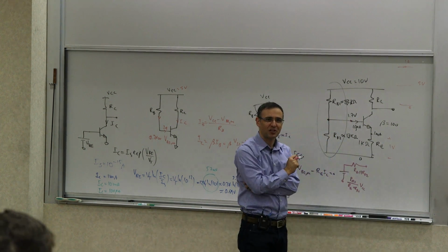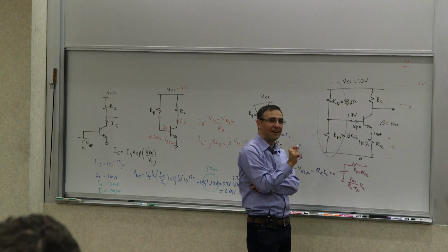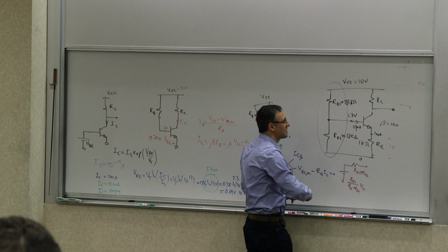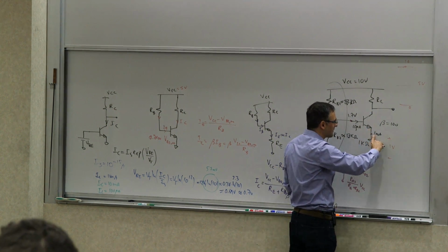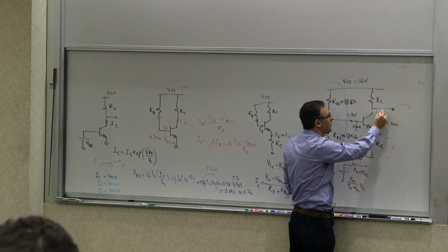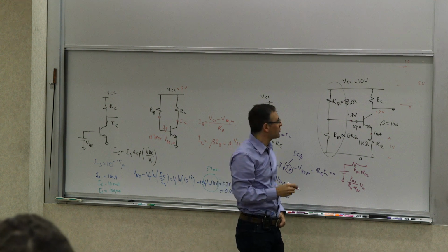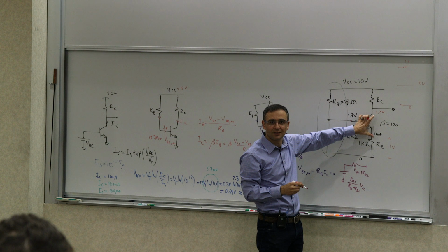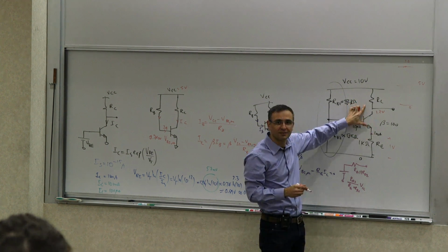Okay, some of you are shaking your heads. Why is it not optimum? That's correct, but why not? Because the bottom is not at 0, right? The lowest this can go is determined by this voltage and this voltage. So even nominally here, this is at 1.2 volts, not 0. And now, when you try to go lower in voltage, you will drive more current, right? So you will drop more voltage here and more voltage there.